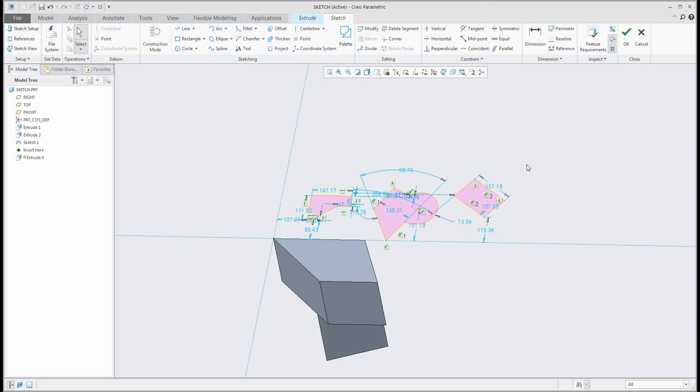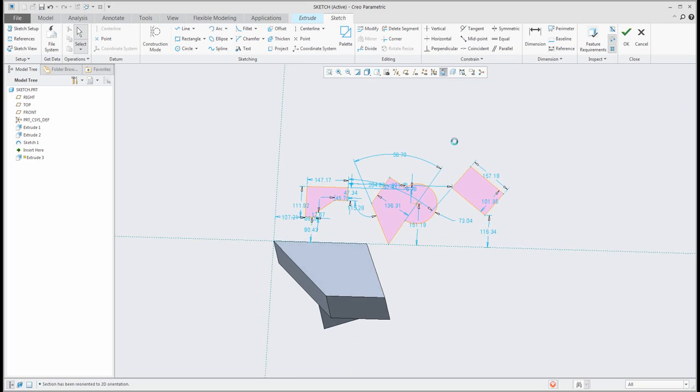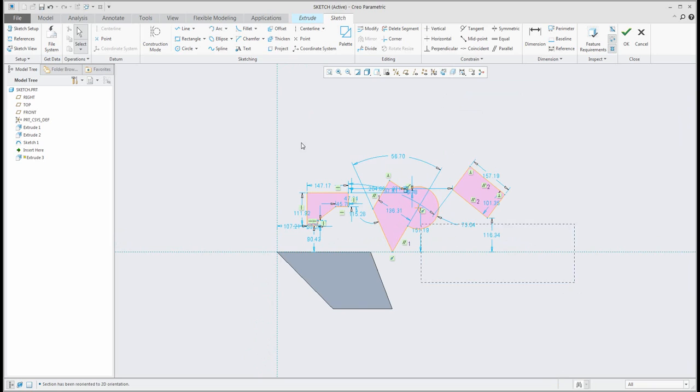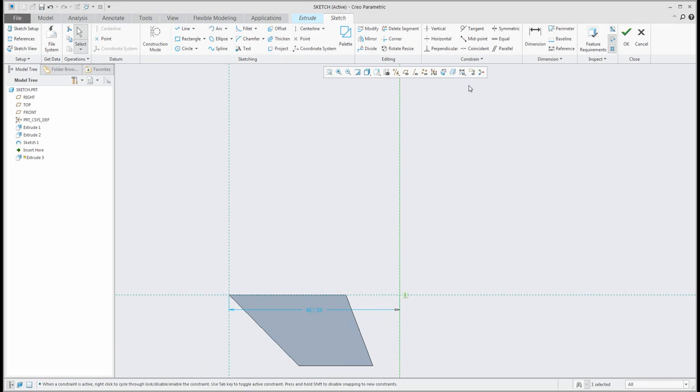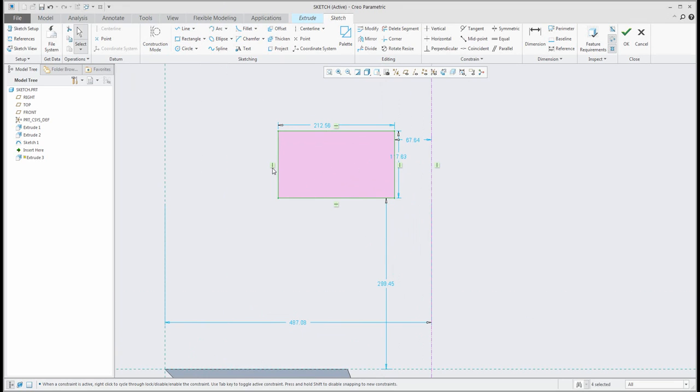And what about the manipulation in the sketch? I will spin again my sketch into 2D. We can delete unnecessary edges, and I'd like to show you how you can work with a symmetric object, for example. The best practice is if you are working with a center line, yeah, because you will create a center line, for example here, and then you can on the left side create some special shape. I will delete that constraints, and we can change the shape here.